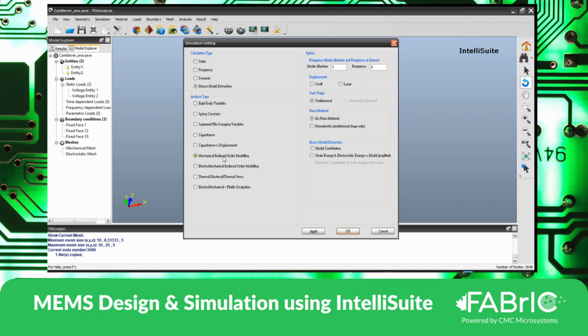Another interesting simulation that we can do is the mechanical reduced order model simulation. What is a reduced order model? ROM, reduced order model simulation, can help to convert the MEMS device file into an HDL, hardware description language, where we can connect the HDL file from FEM to signal conditioning systems or to circuitry.